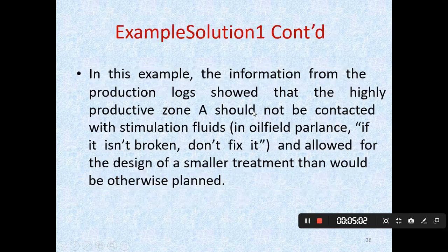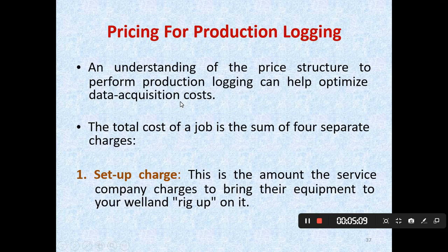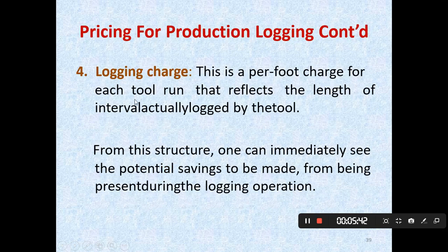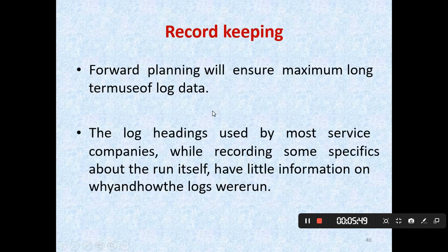So that's the situation when we go for the PLT tool. Now let's look at the cost. First of all, the setup charge: the equipment and parts coming in, or you can say the rig up charges. You need the wireline truck, the equipment and parts, and so on. Second, how much is the pressure of the well? There is a rental fee on the equipment necessary to safely log the well, and the depth, exactly how many feet you want to log. So they charge for the depth, the pressure, the setup, and the per-foot charges.